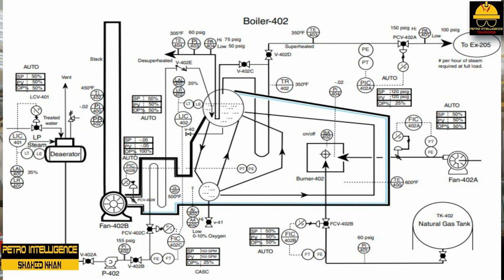However, some operating facilities require low-pressure steam. This is when desuperheating is used. During the desuperheating process, part of the superheated steam is routed through the boiling liquid in the steam drum, cooling it down to a lower pressure. The boiling water is cooler than the 120 psig steam and reduces the pressure to around 60 psig.